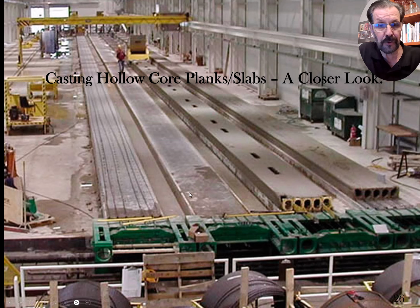So these are pedestals right here and here that they pour on top of, but they pour these hollow core slabs with a zero slump concrete mix, and the reason for that is they don't have any form. It's sitting on a pedestal, but they're using this machine over here to shape it.